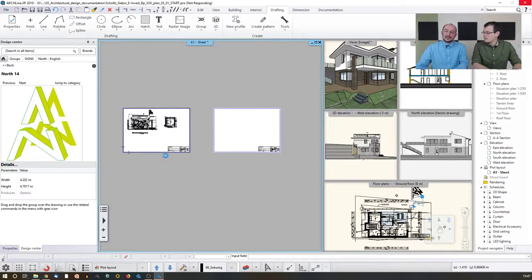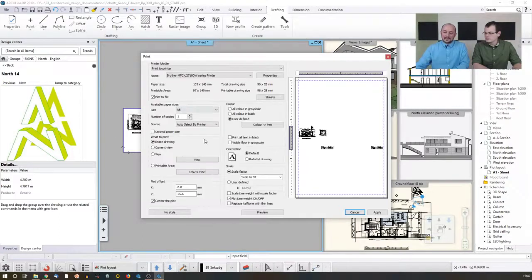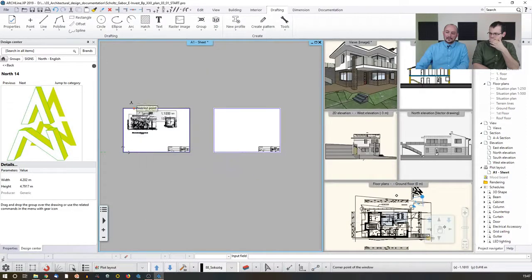Now in this case, instead of adding the whole sheet as a whole, the whole layout as one single drawing with all the pages and so on, you can actually just highlight that content by simply selecting it with the printable area or with the view, for example, here. As you can see now, I can see the whole content, but I just would like to add the current view, click on this one, and then just select this area. So this will be one page, then I add another one as a second page, and so on.